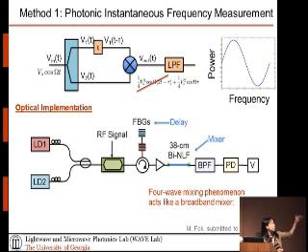So we have two laser diodes combined and launched into the RF modulator, which essentially converts the RF signal into two different optical carriers. And then we launch it into a device called a fiber Bragg grating, which basically is a short piece of fiber like that. It's just 1 to 2 centimeters. So with these fiber Bragg gratings, I can make it such that each wavelength will be reflected back at different timing, so that it provides the timing delay that I need.